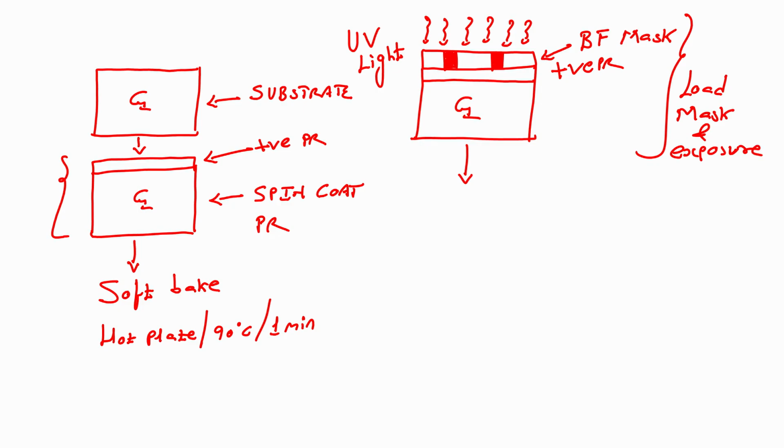After this particular step we will go for unloading the mask. After unloading the mask, the next step would be photoresist developer. You have to develop the photoresist, so we will dip this wafer in a photoresist developer.